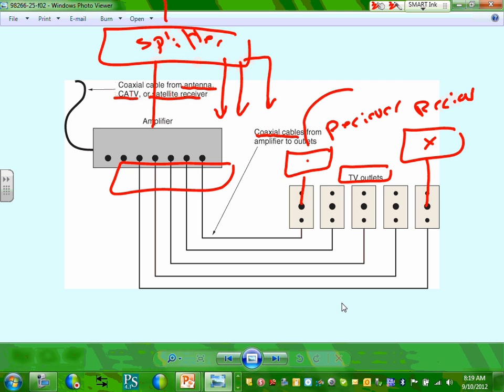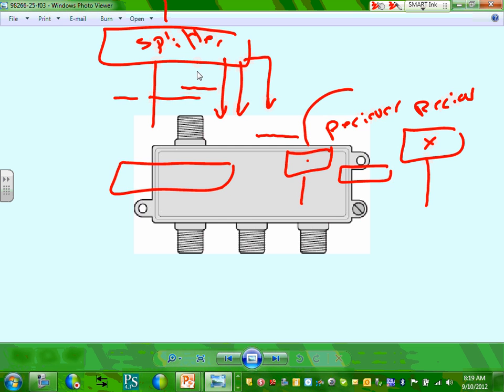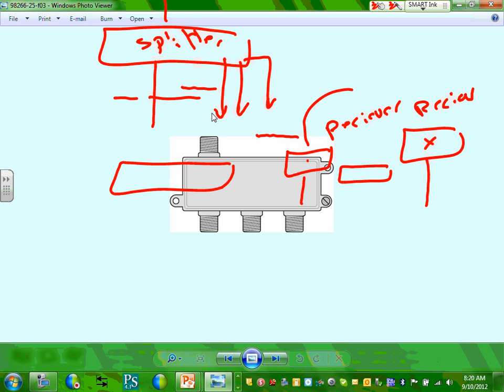Okay. So that's basically what this is. Here's the splitter that we're talking about, guys, the input and the output. I think you can get 2/8. I did the 2/8, so 2 inputs, 8 outputs, or 1/4 or 1/2. I think if you go higher than 2/8, and again, my information might be dated, you might have to go to commercial grade splitters with almost an amplifier. So there's a limit on how many inputs you can bring signal in and split the signal.